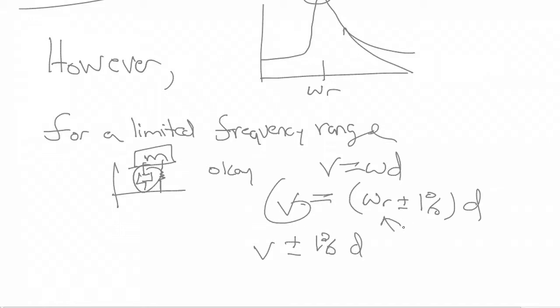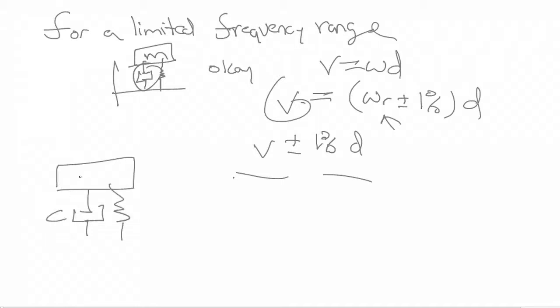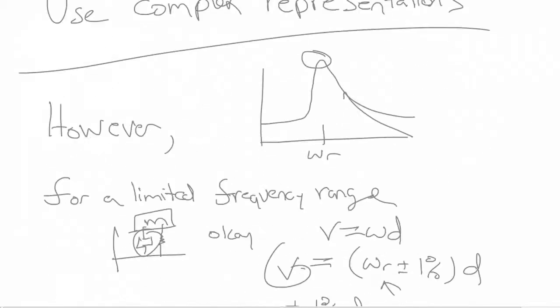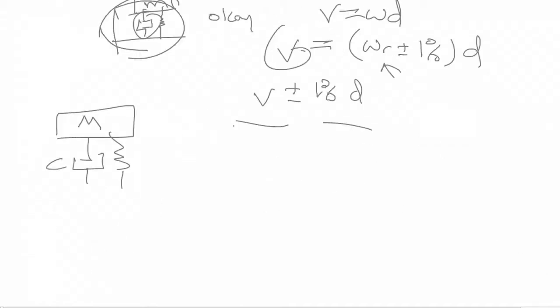Therefore, since the velocity doesn't have much disparity with the displacement with regards to loss, you can end up calculating an equivalent damping factor C for this material system. I may post a different article on that, but if you use this system, it'll still work out. You won't get crazy data. You'll get something reasonable.